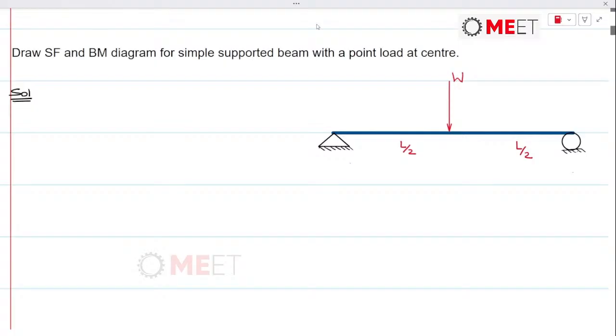once we progress into different parts of the design. So here we begin with, so first is that we are required to develop the shear force and bending moment diagram, which is loaded with a point load at the center. So let's call this as, here this will be a hinge support and there will be a roller support. So we can solve this problem by using symmetry, or we can also make use of equilibrium equations. So let's begin with equilibrium equations.